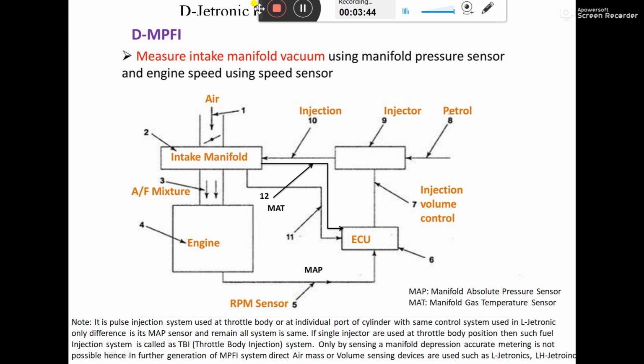So in that sense your injector has to inject continuously in order to fulfill the demand of all cylinders of the engine, because at every phase of the crankshaft revolution, one cylinder or another is doing its suction stroke. So the throttle body injector should send fuel continuously, but not like the K-Jetronic, as it is an electronic system.